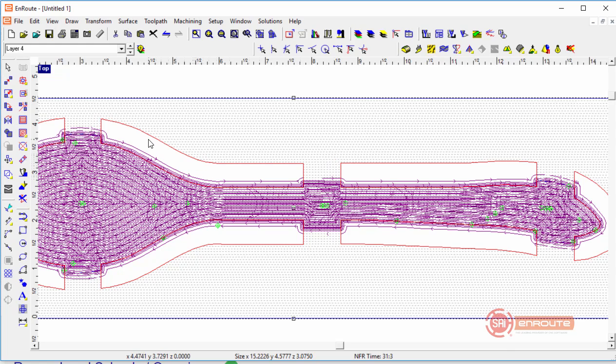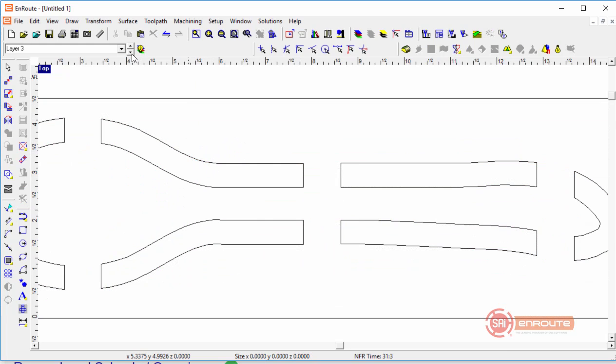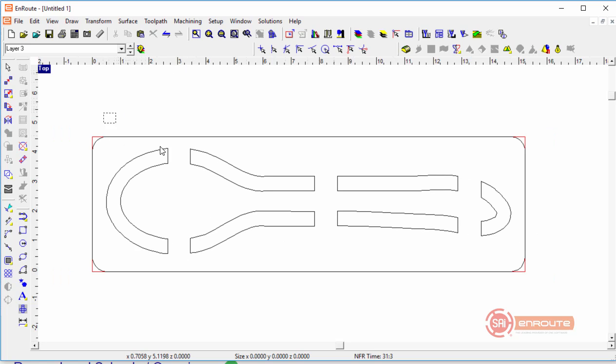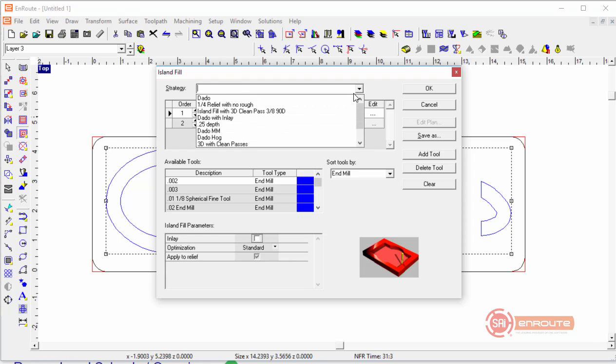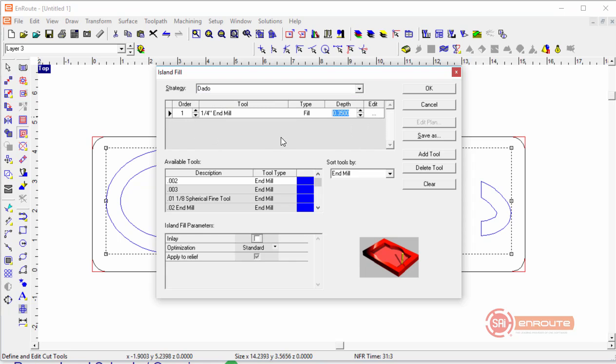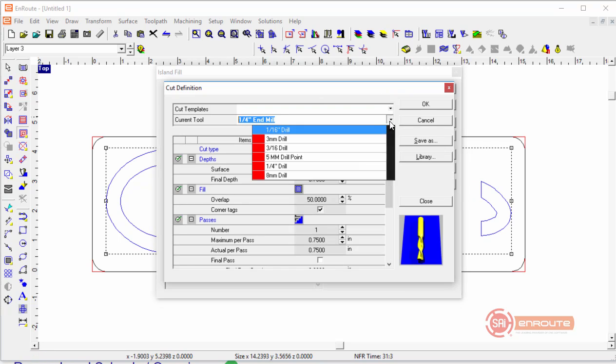All right. And now, if I wanted to, there's probably a ½ inch of this inner part left. So I can come here and grab this. This was side 2, and I'm going to do that island fill. But this time we're just going to go down 0.5, probably. Should be enough. Maybe 0.75. And let's use that long tool for everything.